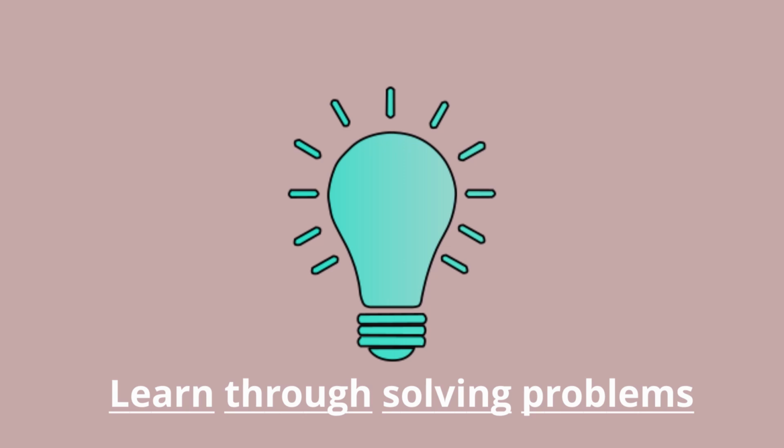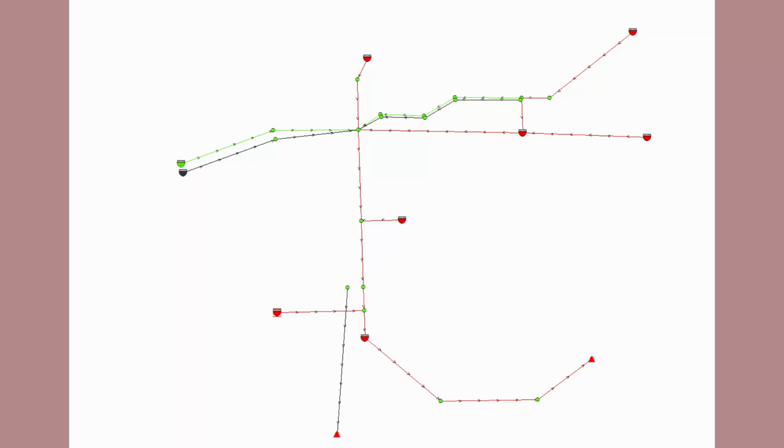I work as a water and environmental engineer, so the problem is about wastewater and stormwater piping systems. The network system is shown here. The red lines are combined sewer pipes, where stormwater and sewage water flows in the same pipe. The green lines are separate pipes, where there is only sewage water, and the black lines are stormwater pipes where stormwater flows. This network has been simulated, so there exist model results regarding flow conditions and water levels in the pipes and manholes of this network model.